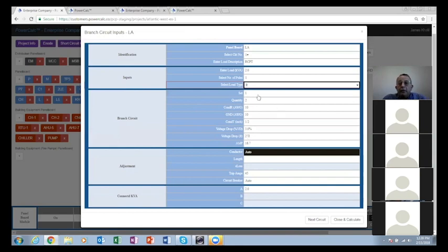So it already displayed to you what the branch circuit is going to be automatically. All these are automatic values. So it's one set, two number 10 conductor, and a number 10 ground, and a 1/2 inch conduit. Okay, and that's all what you need to do. All I need from you is the 3 inputs: the load KVA, the number of poles, and the load type.